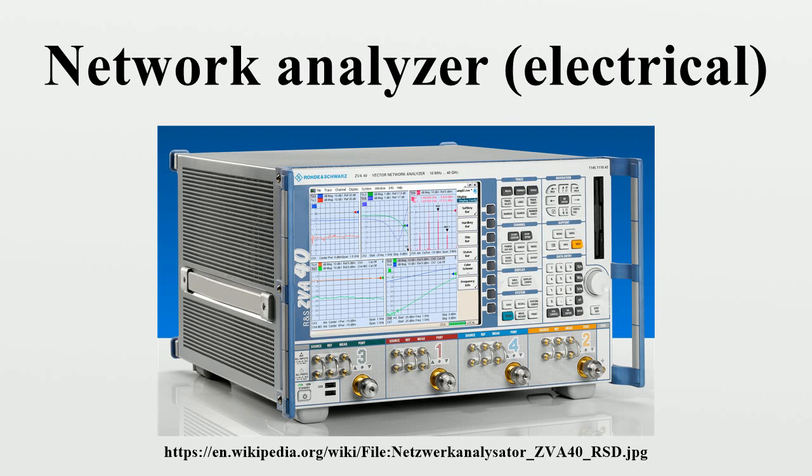In some calibration kits, the data on the males is different from the females, so the user needs to specify the sex of the connector. In other calibration kits, the male and female have identical characteristics, so there is no need for the user to specify the sex. For sexless connectors, like APC7, this issue does not arise.